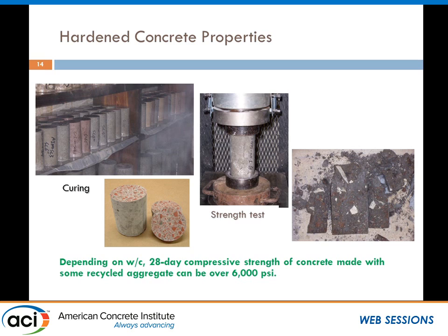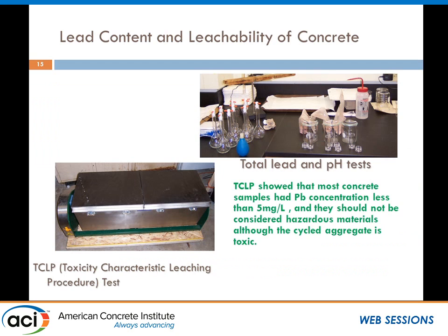That's hardened concrete. All these things we go through standards, curing, strength tests, and one thing I do want to point out is that on all the breaking samples, you see that a lot of those breaking surfaces are on those painted surfaces. That's expected because the surfaces are smooth. But still, most of our strengths are quite reasonable, and we can get as high as 6,000 psi.